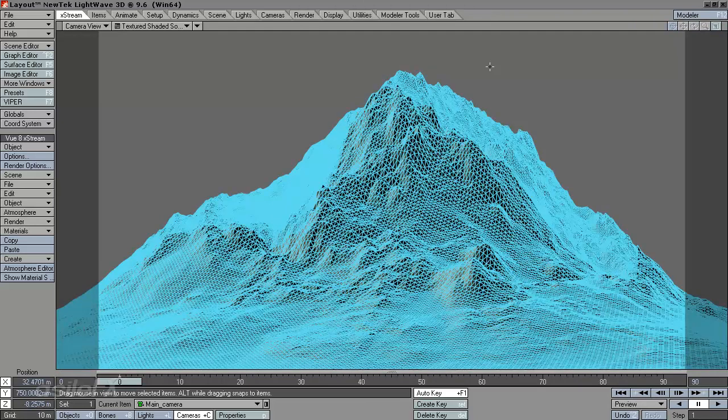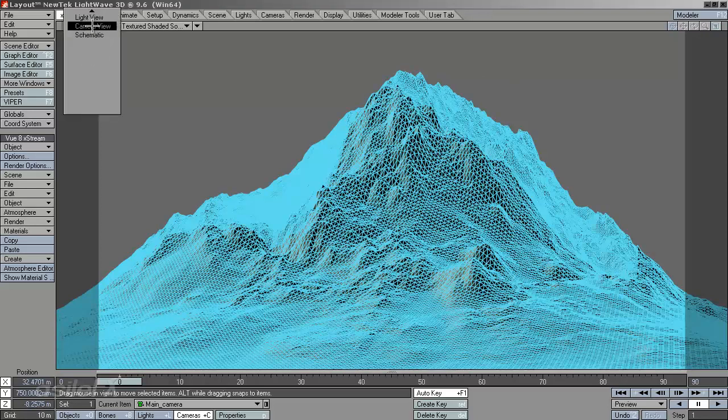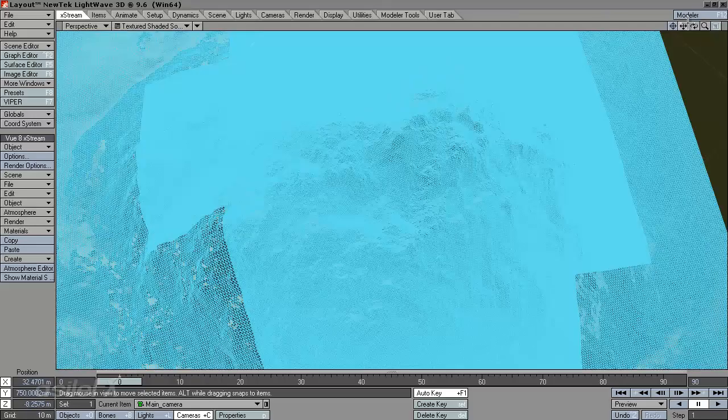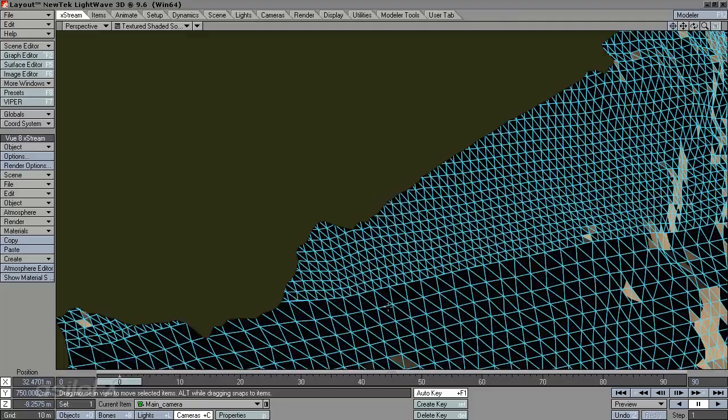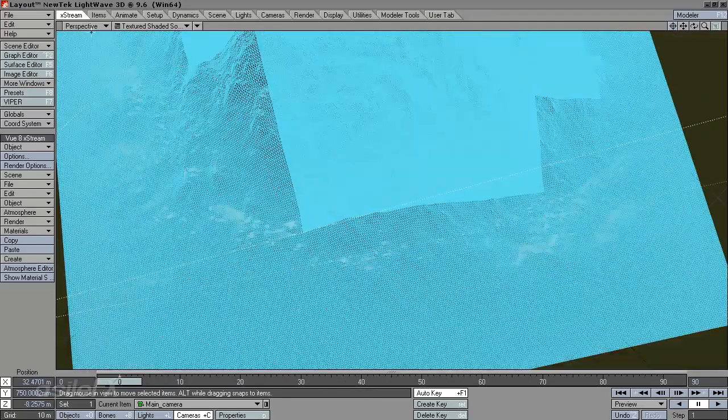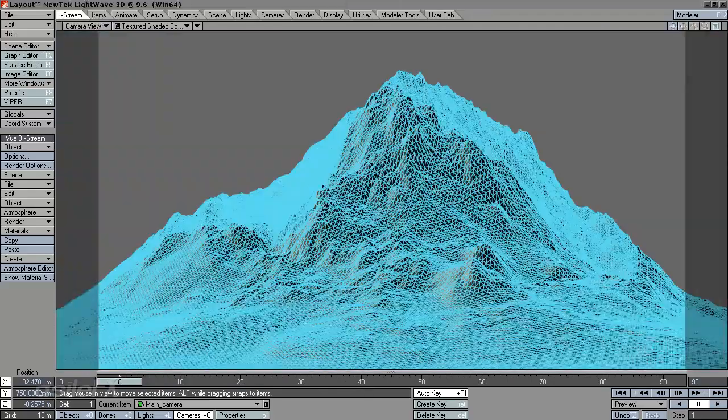Now if this will work for you, and this would work quite well, the only problem is because of the variation around where the intersections are meeting between the different resolutions, those objects and polygons will not connect correctly, which means there's going to be gaps in the object. And for the most part, we just don't need this high quality of an object as a collision, really depending on the effect. If you were going to have it hit every single tiny bump on the way down, then you're going to need something a little more high res.